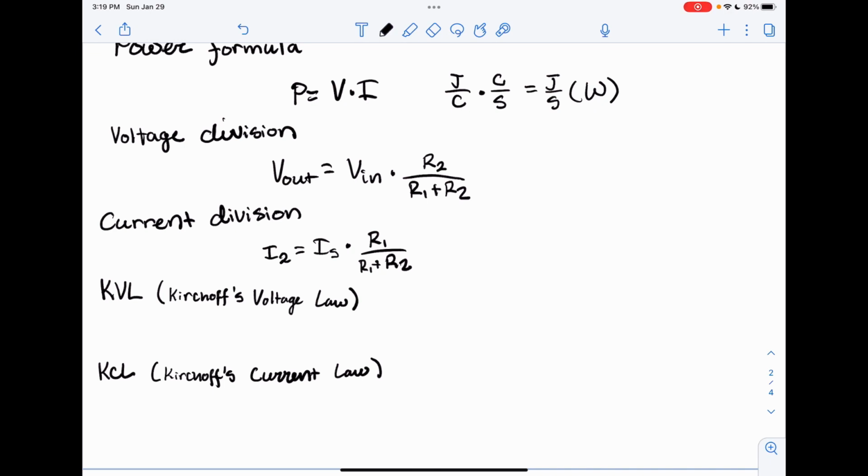But an important aside for those of you who are here to learn a little bit more about the context of circuits in fire alarm: this concept of voltage division, this voltage divider formula, is very useful when trying to design a zone circuit or a NAC circuit. The concept of the end-of-line resistor and the base resistor in the panel comes from voltage division.